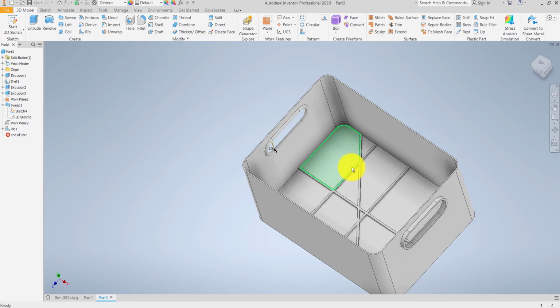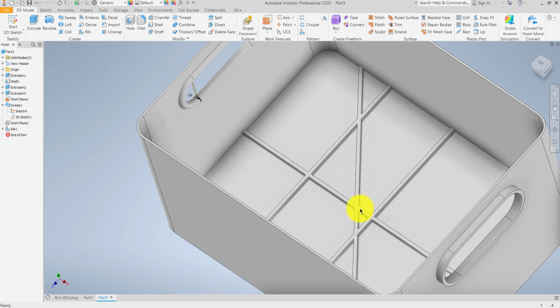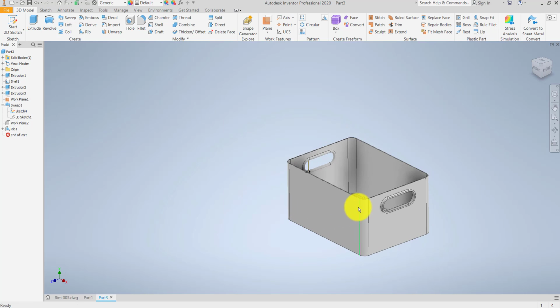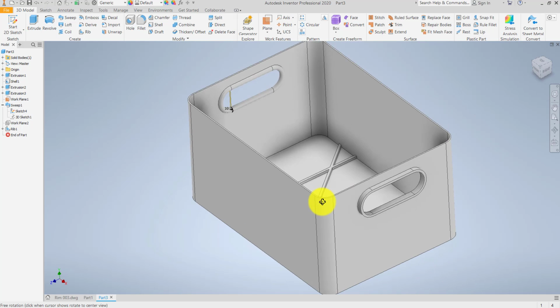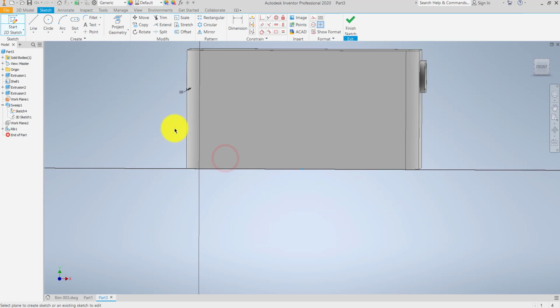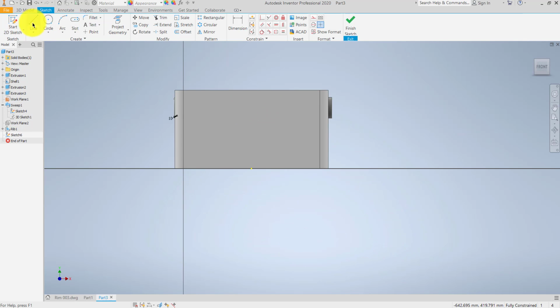So yeah, that was rib. If you want to use the rib here, you have a small problem. If it was SolidWorks, then you don't have a problem. But if you have Inventor, you will have a problem. The problem is Inventor needs the boundaries. So what you have to do is say, I want to sketch here. Maybe you want to sketch some sort of